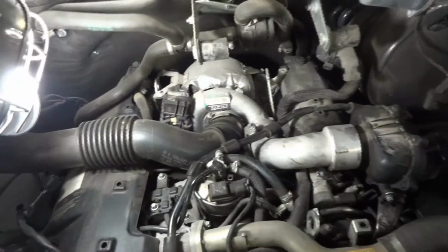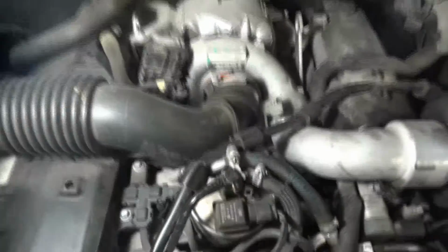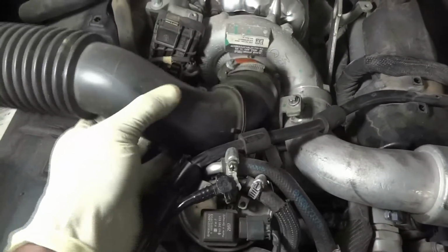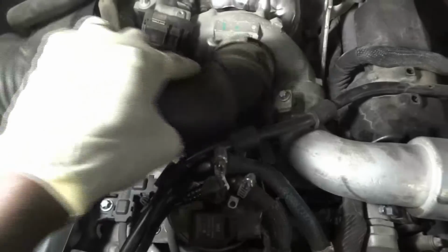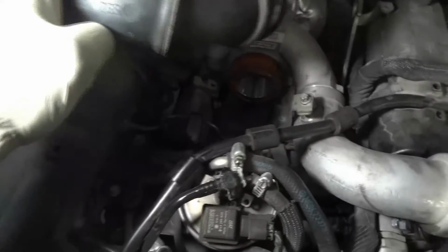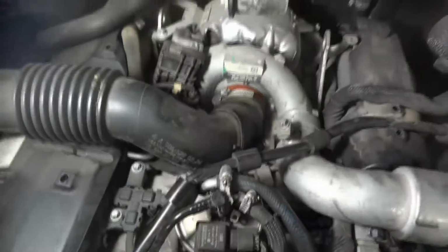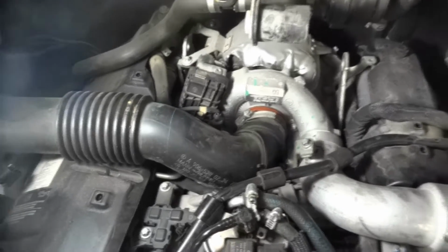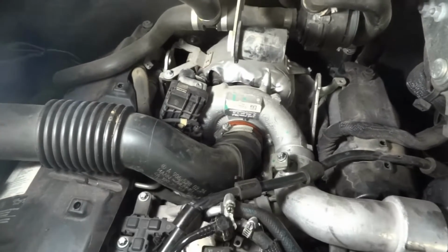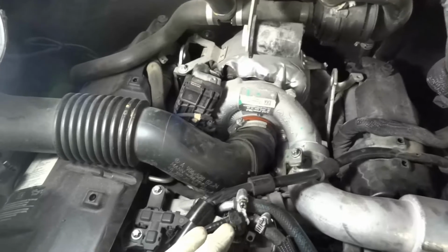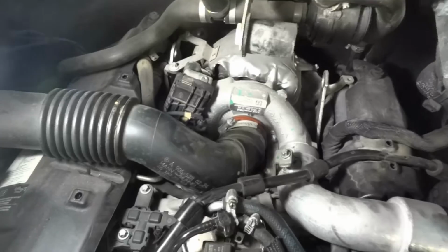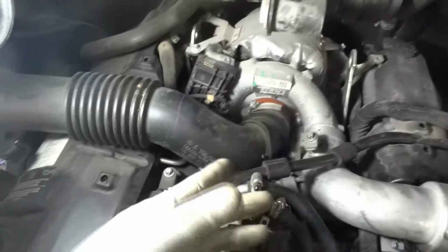And guess what, guys? See this right here? So this thing was completely loose. Oh my gosh, it completely came off. So that's why it was sticking out. So this is the issue right here. Did you see that? So that's why it gave us that 2355 code. And remember, when we were looking at the code description and the possible causes, one of the possible causes was a leak in the intake system. So right here, this is a leak.